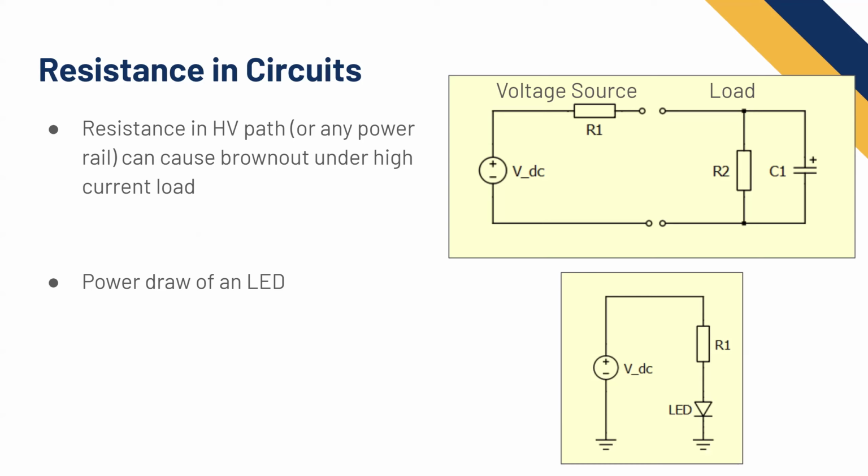So we want 4 milliamps to go through here, and we know the voltage drop needs to be 4 volts, right? So then we just go back to Ohm's law. You put your voltage drop equals current times your resistance. And so 4 volts divided by 4 milliamps, it's going to give you a kilo ohm.